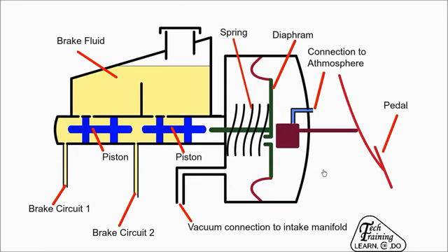As disc brakes do not have a wedging action similar to drum brakes, considerable effort is required to operate them. Usually a car will have a braking power assist system. This uses the vacuum from the air intake system.